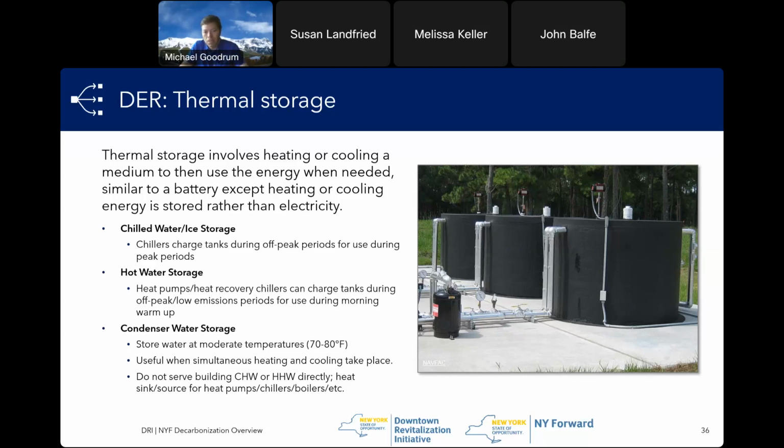And so you're running one or two pumps instead of all the other HVAC equipment. Shaving it means that at those peak times you may be running your HVAC system, but you also have a tank and you can supplement with that. So instead of the HVAC system having to meet the entire load, it can meet like 75% of it, which can also mean you can buy a smaller system. So it can be a really powerful strategy, I would say, if you are considering thermal storage.